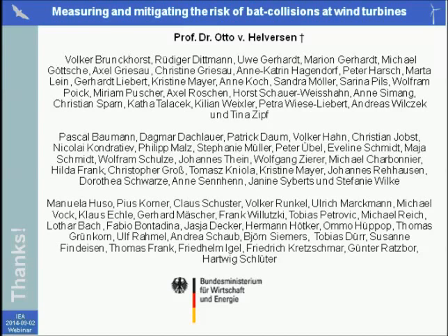This is what one day would look like in this experiment. In black you can see the wind speed, rather low during the first half of the day, a bit higher during the second half. In red you can see the mitigation cut-in wind speed defined by our algorithms, only for the night of course, because bats don't fly during the day. And in green you can see the rotation speed of the turbine, and when the rotation speed is higher than 4 rotations per minute, the turbine is running normally.